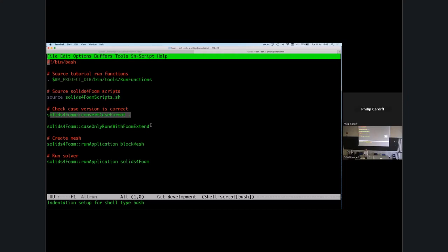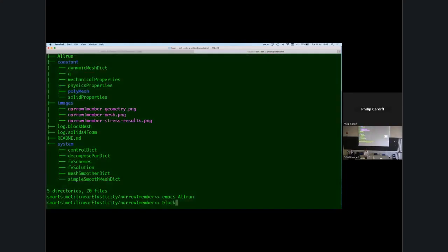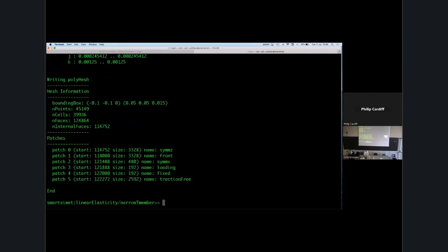So this won't work in general for any OpenFOAM solver. And sometimes I'll have a function where some of the choices will only work with one version of OpenFOAM. In this case, this particular block coupled solver only works with foam-extend, so it will just quit with a silent warning that you can't run this if you're using a different version. Okay, so I'm using foam-extend 4.1 for this.